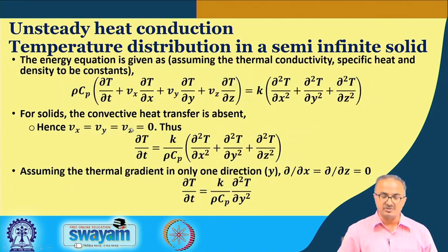With these assumptions, we again consider the energy balance equation, and we know that temperature is a scalar, so we have only one energy balance equation. In it, these are the unsteady state term, the convective or inertial term, and the conductive term, and we are neglecting any source term, that is, any kind of generation.